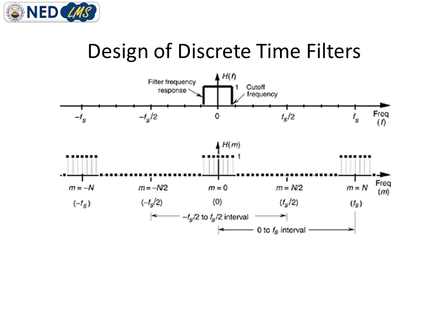So we need to take a DFT or FFT of this discrete frequency plot, and then we will obtain the time domain impulse response, and those impulse response coefficients will be used to design the filter.